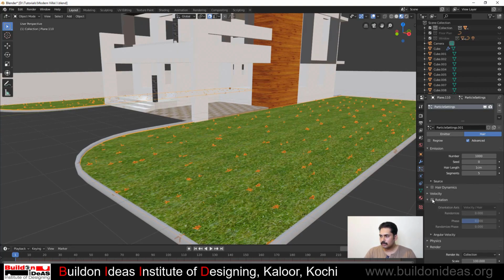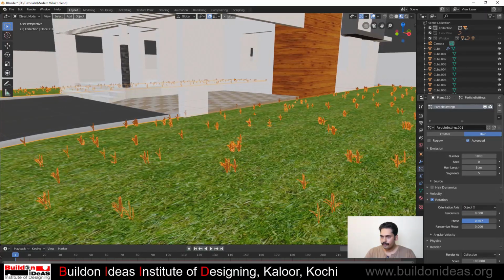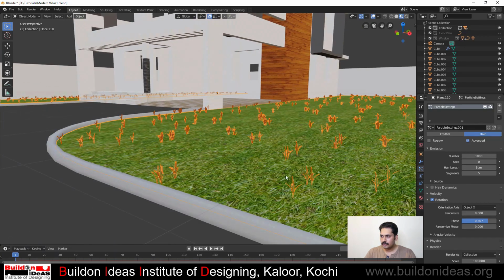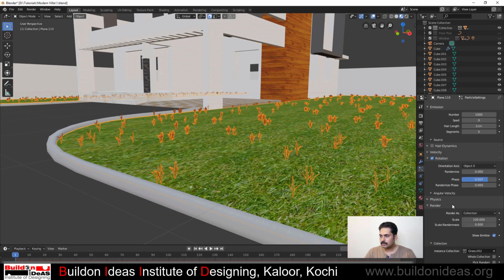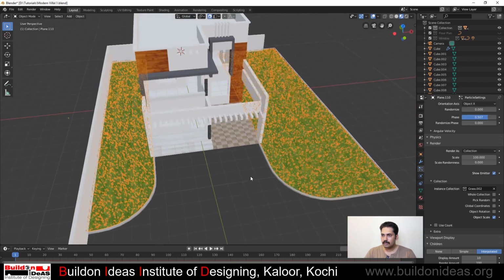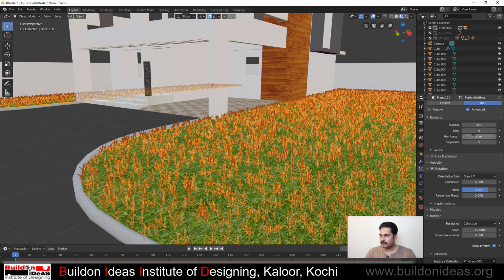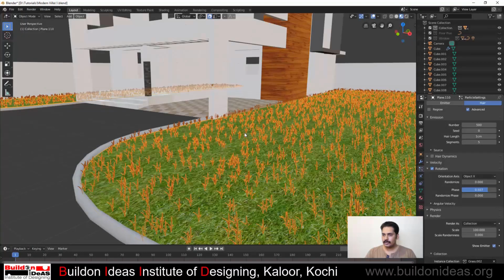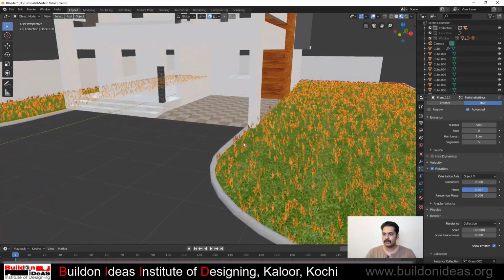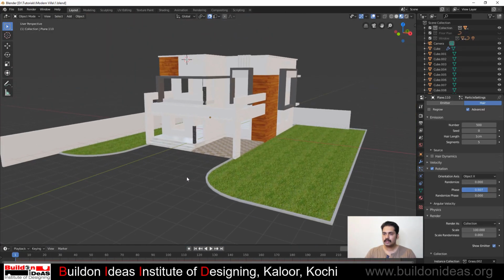Now go to the rotation, and click rotation, global X. Yeah, it stands up. Then find the children in that, and make it interpolated, so you can see it very well. The grass is very much inside, and what you have to do is reduce the number from 1000 to say 500. What you see here is only 10% of what is going to actually come out. So this is more than enough to see, and then finish it up.